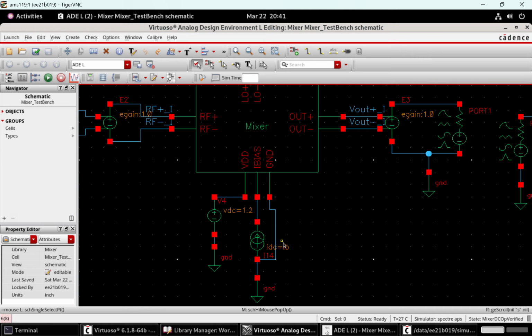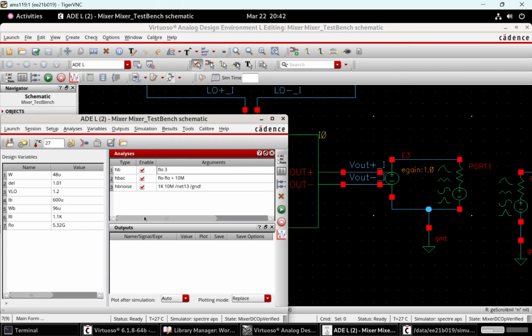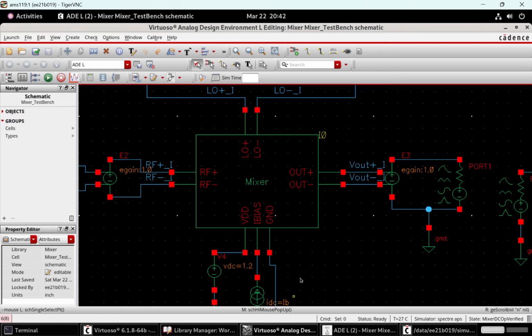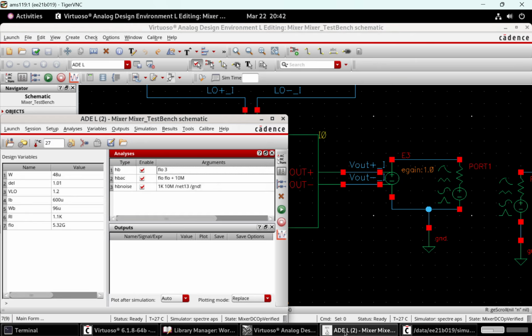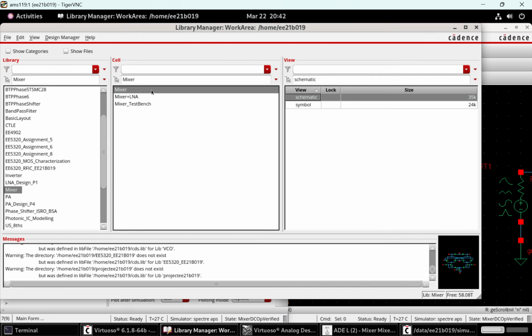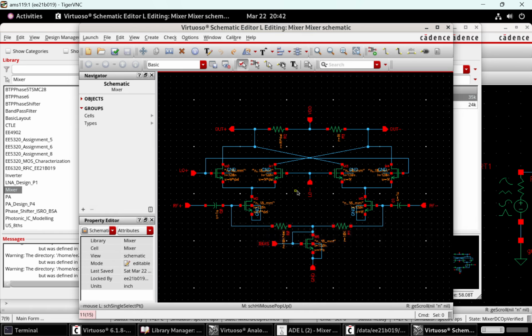And the other supplies are provided to the mixer, and its output is taken across this, as we saw in the case of an LNA as well. The setup is also the same. However, I've added a mismatch in already. It is not necessary that you already add the mismatch for noise figure, gain, etc. They will not severely attenuate your spec.